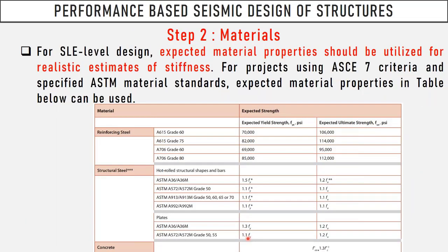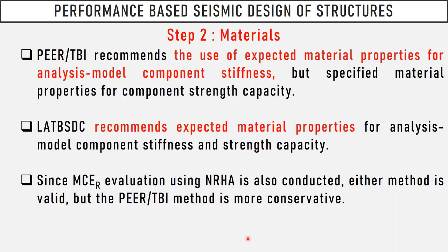This is the approach, for instance, for service level earthquake: expected material properties and more realistic stiffnesses, because we all know that reinforced concrete will crack. That's why it is more acceptable and advisable to use cracked section stiffness. Don't forget,